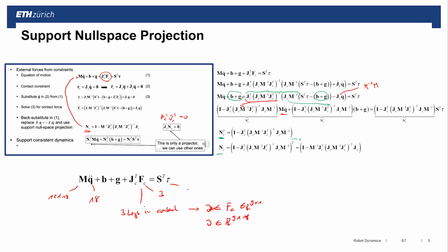In my actuator, I have 12 torques that I can produce. So I have 18 motions, 12 in torques, and 9 in forces. Now this Jacobian can maximally block a 9-dimensional subspace. So that leaves me with another subspace where I can just control the motions with the torques.